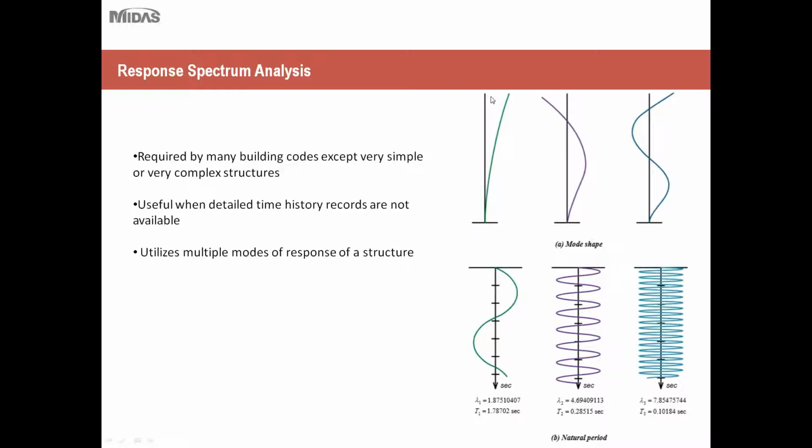Here you just have one mode to represent this one deformation. But here you would have, I believe, two modes to represent this type of deformation. And then finally, maybe you have a critical stage where the earthquake is at its strongest, at its fastest, and then you'd have something such as this. So you'd have maybe up to three or four modes. Just keep in mind that depending on where you're at with the earthquake, your structure could be under a different type of loading. Those of you who are very familiar with seismic analysis will know that when a building or any type of structure is subject to seismic loading, the way that the loads are oriented really starts to shift.